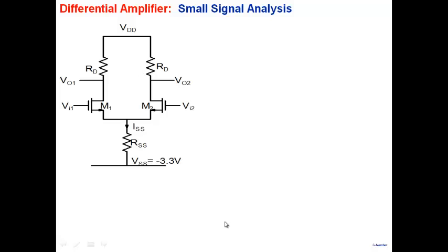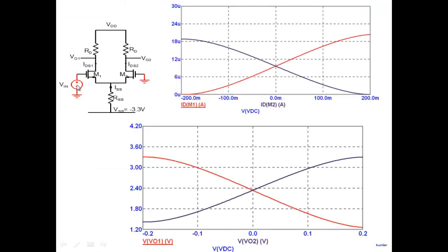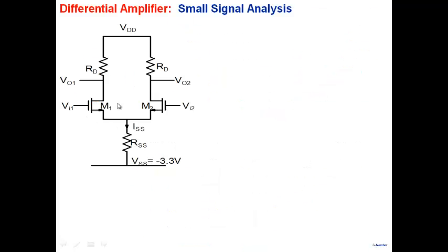And as I said, this is more interesting when you use a differential pair for switching applications. When you apply large voltage here, then only one is interested in this kind of characteristics. Normally, we use a differential pair as an amplifier and the voltages that we apply are small in magnitude. Therefore, small signal analysis is sufficient for us to find out the values of currents and voltages in the circuit here.